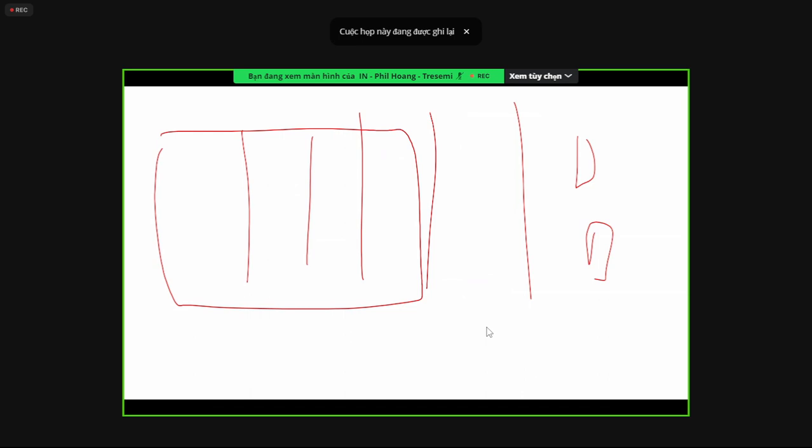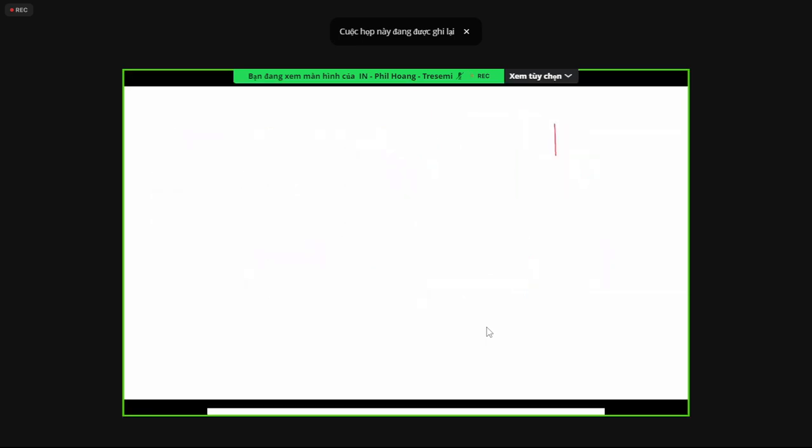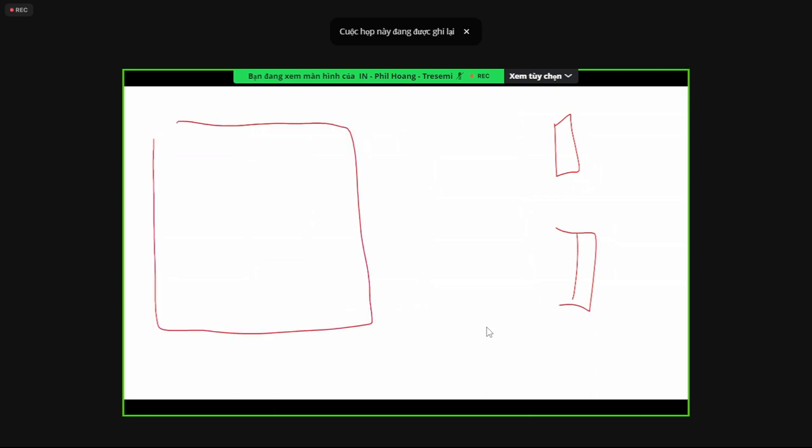But if you have standard cells vertical, and then because of the floor plan you have to rotate the macros, and now your macro orientation is like this, the inner transistors are probably like this. Then you violate the design rule.